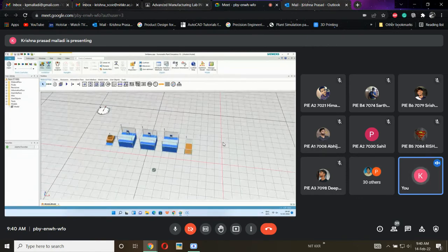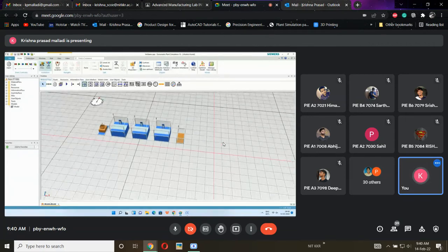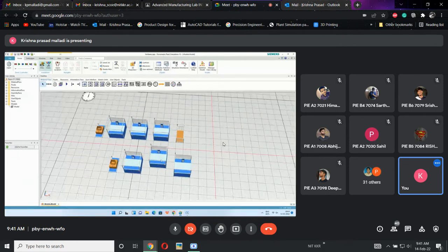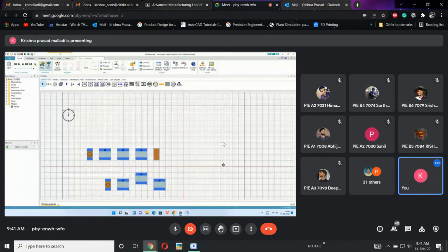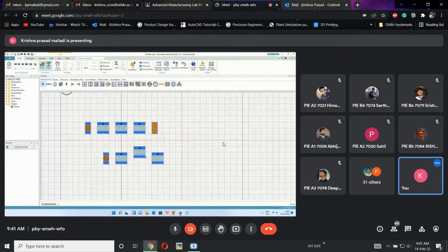You can directly create in 3D also, but sometimes in 3D, if I place one, maybe some disturbance will happen, maybe some geometrical distortion like this. You can drag like this also. See what is happening. Sometimes you won't get the exact point. So to get the exact point, you need to convert into planar view. For that, you need to press P. Again, you can draw and drop.